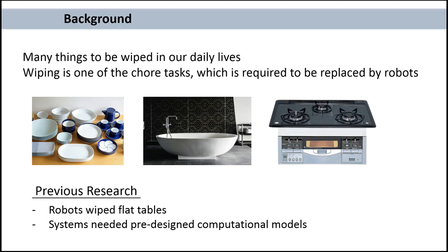In previous research, many of them are limited to wiping only flat tables, or some research which can wipe 3D objects needs pre-designed computational models. To the best of our knowledge, our work is the first study that enables robots to trace various unknown 3D shape objects by only learning sensory motor information.